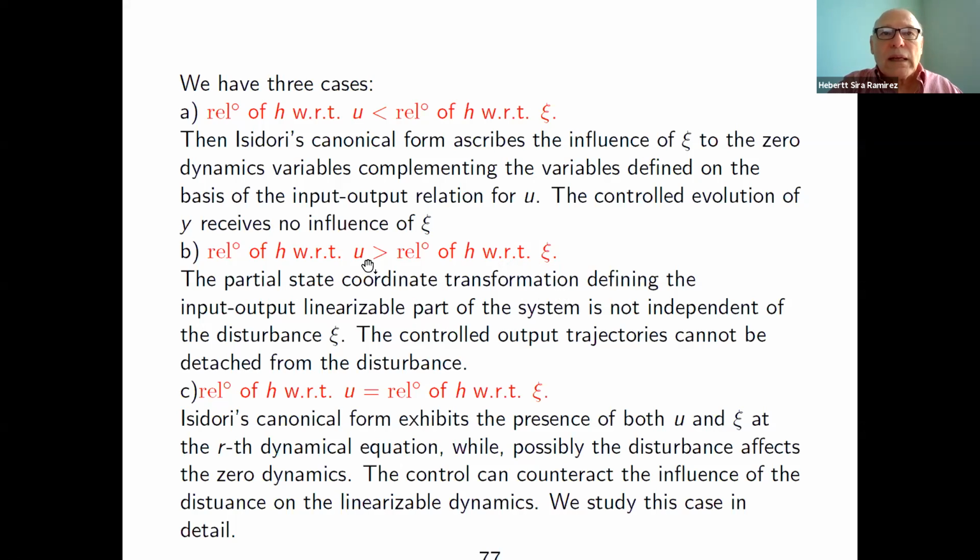In this case, you're still able to establish the linearization and provide a design that stabilizes the output, but you have to be conscious that the zero dynamics is now getting to be a little bit more complicated because of the confined presence of the disturbance in those variables described in the complementary dimensions of the input-output linearized system.